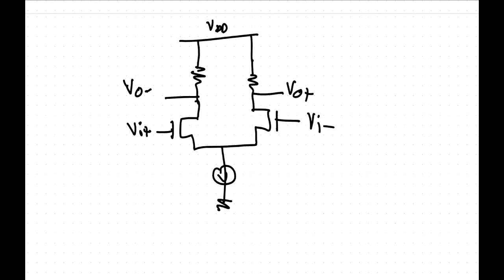You don't get a lot of gain, because you don't have that really high output impedance, but you don't need common mode feedback now. So there are exceptions, and you can build circuits around that. But if you do this, it's harder to have high gain. And also the common mode is fixed, right? Because the more current we draw through, the more voltage drop there. Yeah, you can't separate your gain from your common mode, for instance. Yeah, that's right. But they will be defined.